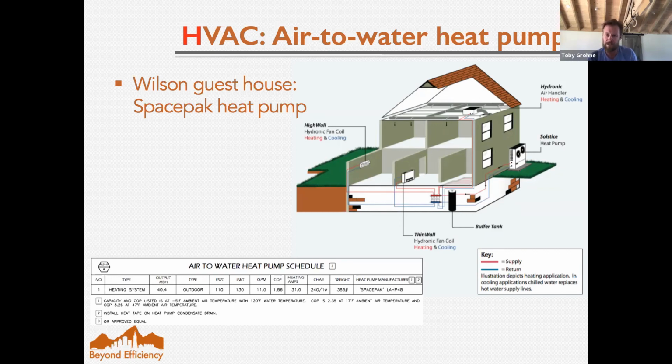If you've got a client that's going to insist on in-floor heat, it's the best way to provide it. So if it's a larger home, I would say going with the air-to-water heat pump, and then you can pull your domestic off of that system, as opposed to going with the heat pump water heater to heat your floors.